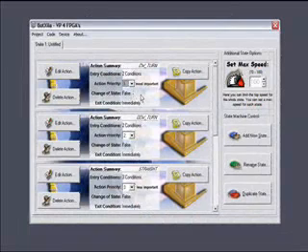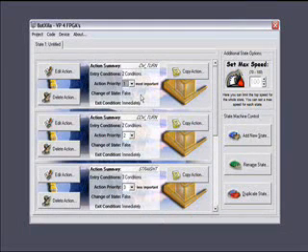We can modify the priority of each action by selecting on the indicator the place number that we want it to take. To add more complexity to the algorithm, we will make it stop once it gets to a white line that covers all three bottom sensors. For this, we will create a new state that only has the action to stop, so that once the robot has stopped, it shall not move again.